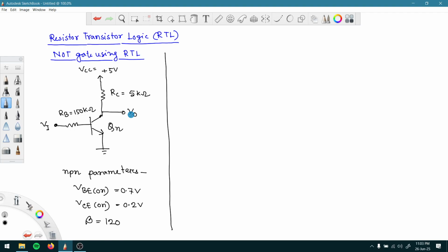So we will repeat the discussion we had in that lecture: if you increase the voltage at Vi from 0 volt up to a higher voltage, how the output behaves. That is the voltage transfer characteristics. We will draw a graph where the x-axis has the independent variable Vi, and with the change of Vi, how VO or V out is changing will be plotted in the vertical direction.